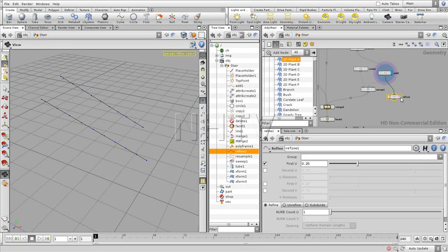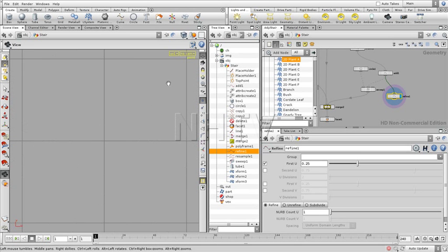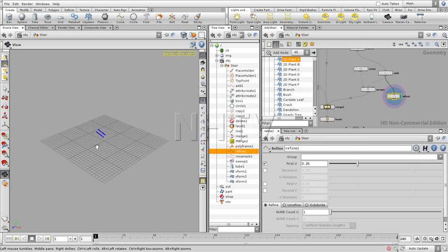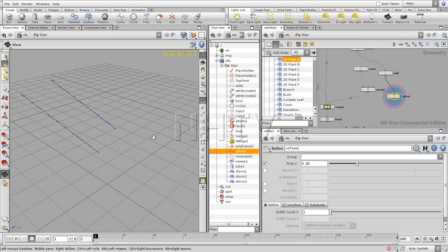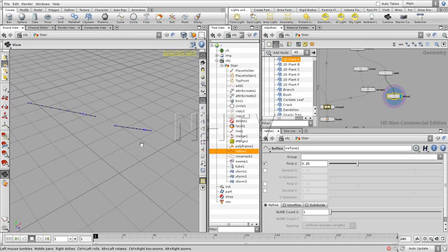and what this refine node does is the following. First of all, you set an influence area using U and V. This is a parametric U and V, so it's not a UV that you can see right in the viewport. So if you press spacebar 5, this is the UV viewport. You don't see any UVs being applied yet. But that doesn't mean that this object doesn't have any parametric UVs.